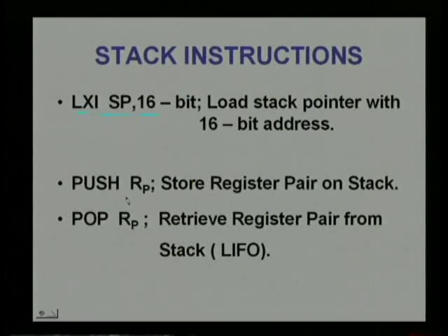Next, push RP. This instruction is used to store register pair on stack. We can store 16-bit data on the stack at a time. We cannot store single byte of data. And next, pop RP. This instruction is used to retrieve register pair from stack, and we should remember it works with last in first out.